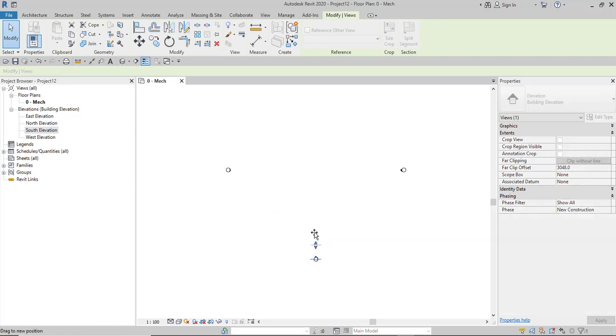But I want to expand it and pull it out. When you pull it out, you see that this value will update to 3423. I can always pull it out to the back here and get about 49,000, but let me put a flat value of say 48,000. Okay, enter. So I have 48,000. So I can select this marker, control-select this elevation marker also, and then this one also, and then give all of them an extent of 48 meters. Enter.